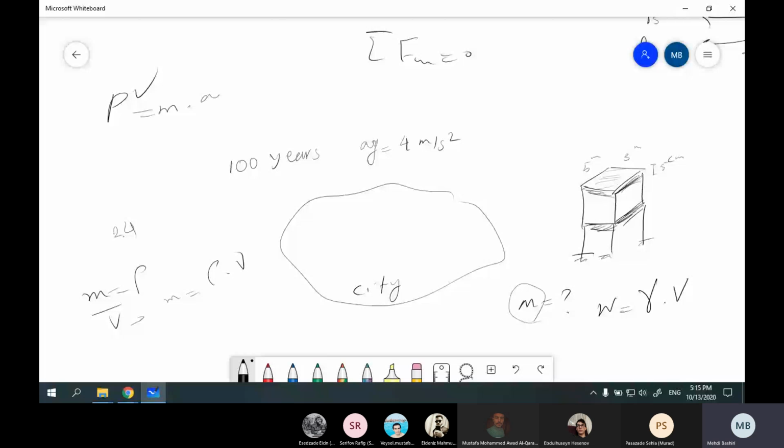For example, you want to design your columns. We simplified columns with springs, so the target is to design your columns. Also about the damping, you can't do many things, because somehow it is restricted. Mainly we assume 5%.